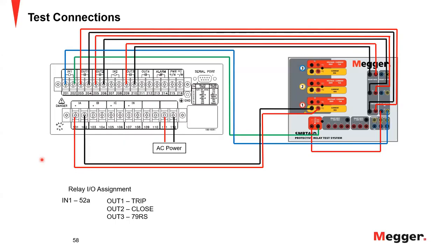Thanks. So our next question is going to be for Sughosh. Do some test templates exist for reclosing tests in the RTMS? Yes. What we have is, like you already saw what Mike showed, we have the state sequencer feature that by default is set up for a two-shot lockout testing. And we also have these test templates that are embedded in the relay test plans. Based on the settings you read for the 79 element, it is going to automatically configure the template for your testing. So yes, we do have the templates.